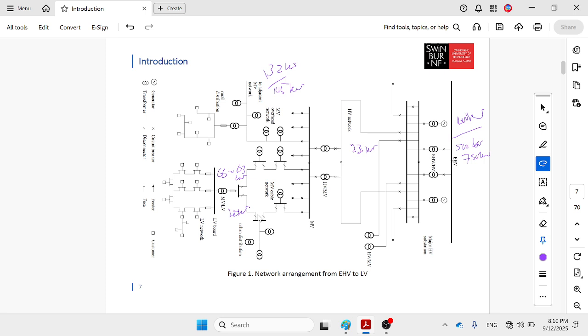inside the premises, such as the university, we have a multi-level. We have a transformer close to the multi-level parking, which is 20 to 11 kV. Sorry, that one is 11. Before that one, we have a transformer close to the roundabout around the university, 20 kV to 11. So inside the university, an 11 kV to 415 V transformer is available close to the multi-level parking. So different places.